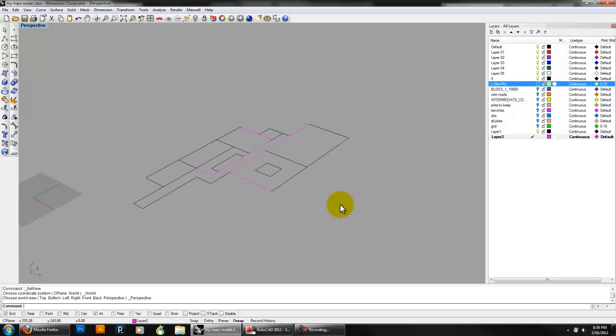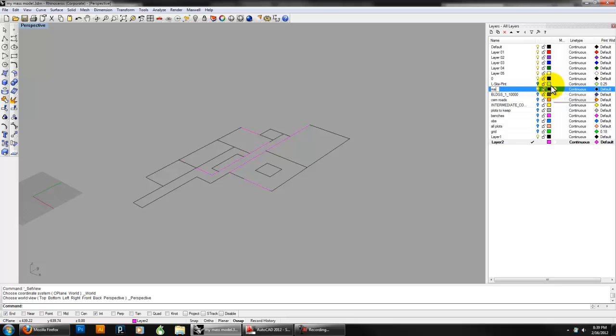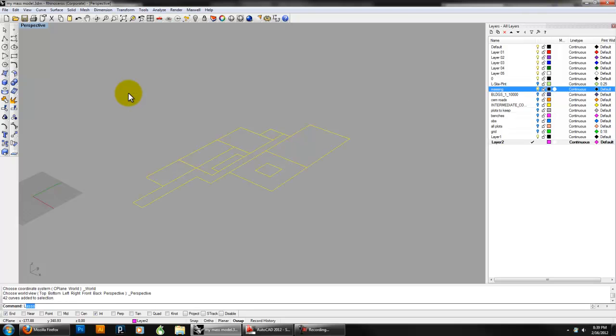So a technique that I'm going to do is add a layer called massing. And I'm going to go ahead and lock these. So lock, LCK. I'm going to do that because when I'm in Autocad, I'm not always making closed shapes. I'm not always aware that they're not full shapes. They might be a couple of segments. Maybe these aren't joined together. And what I want to do in Rhino is use these as an underlay, and use my endpoint snaps to basically redraw them or trace them so that I get exactly what I want. Okay, and it'll make more sense as we go on.